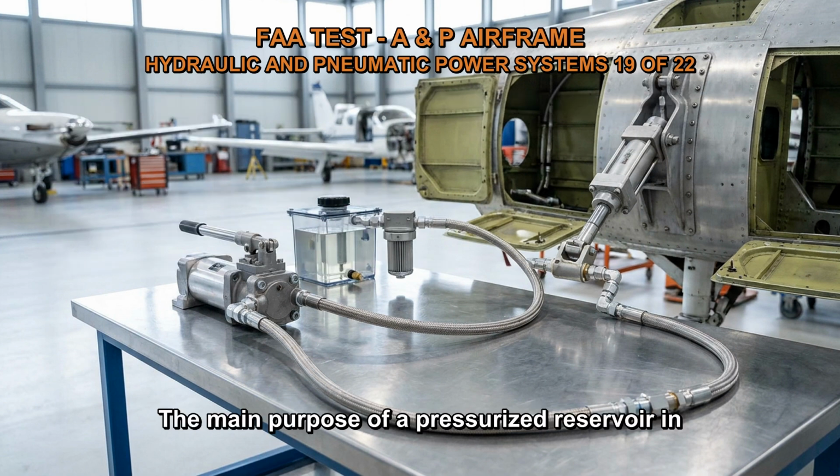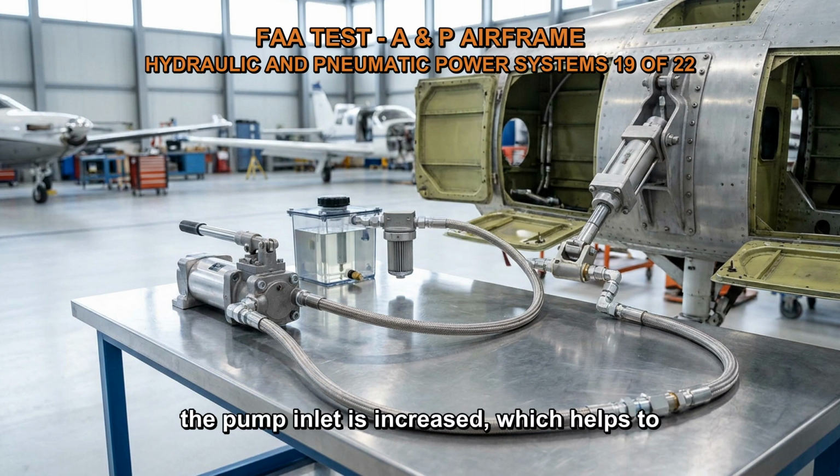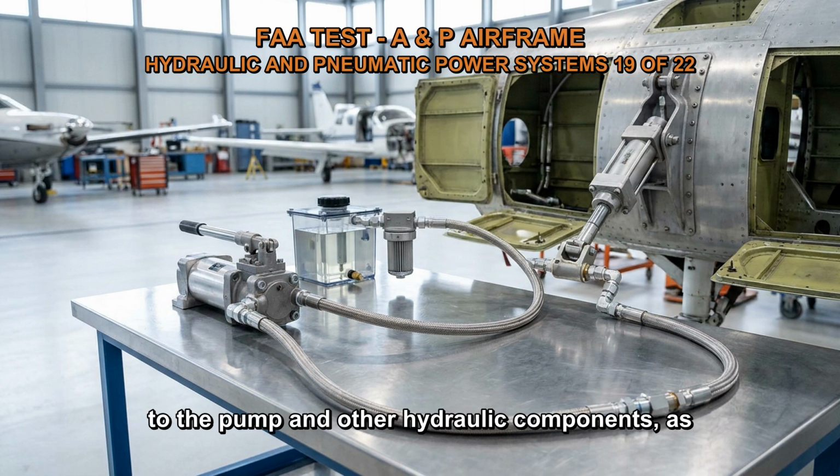The main purpose of a pressurized reservoir in a hydraulic system is to prevent hydraulic pump cavitation. By pressurizing the reservoir, the fluid pressure at the pump inlet is increased, which helps to prevent the formation of vapor bubbles and cavitation. This is important because cavitation can cause damage to the pump and other hydraulic components, as well as decrease system performance.